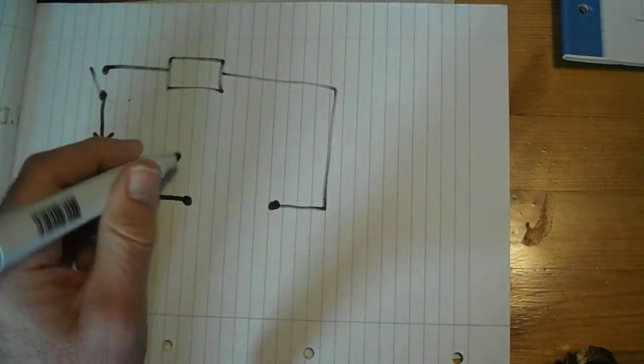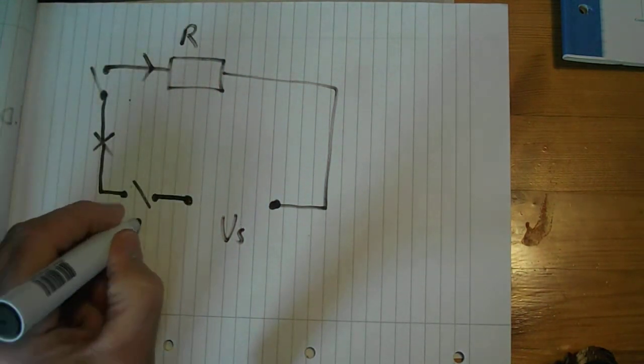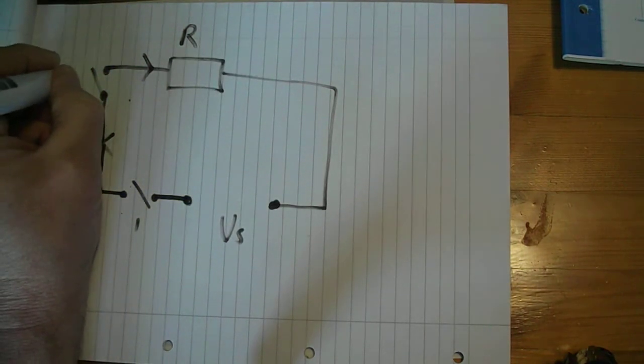However, in your network, because we're working on low and high voltages, but they're nevertheless dangerous voltages as far as you're concerned, we have to have a way of isolating the circuit, and that's done with this symbol here, which is an isolator, and then we have a protective device which is a circuit breaker, and then we have a switch which is shown like that, and there is our load or our customer. So there is VS, there is the current, there is the load, and you've got 1, 2 and 3.